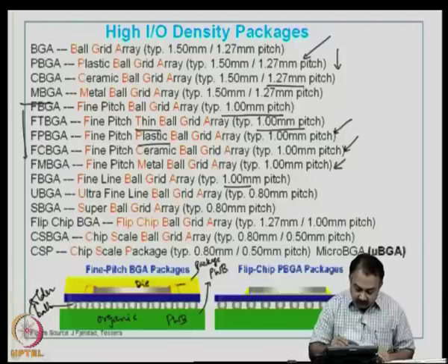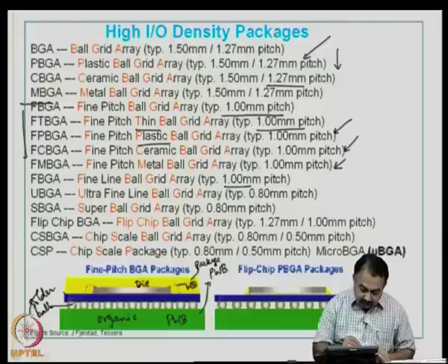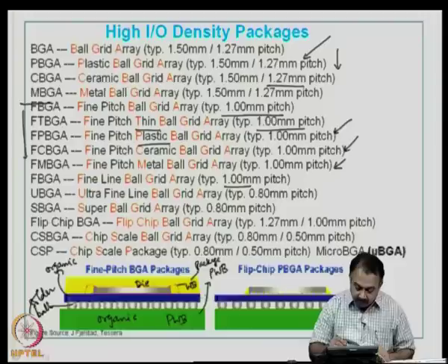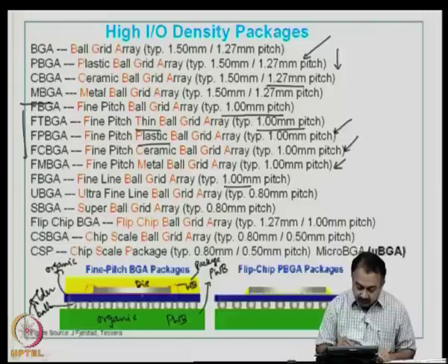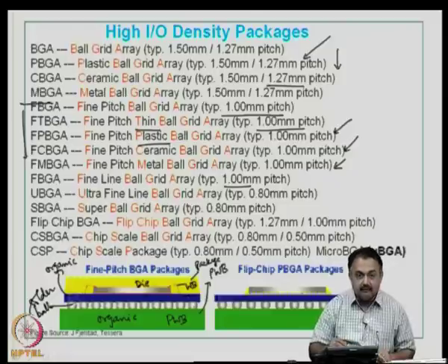Then you can see here a typical wire bond, let us say, and then in between the die and this blue area that you see here is an adhesive which attaches the die, and this is again an organic substrate. This organic substrate is typically about 4 to 8 layers of construction. What it basically does, as I mentioned before, is that the IOs of the die are fanned out through this entire 4 layer or 6 layer or 8 layer substrate to terminate in a solder ball.